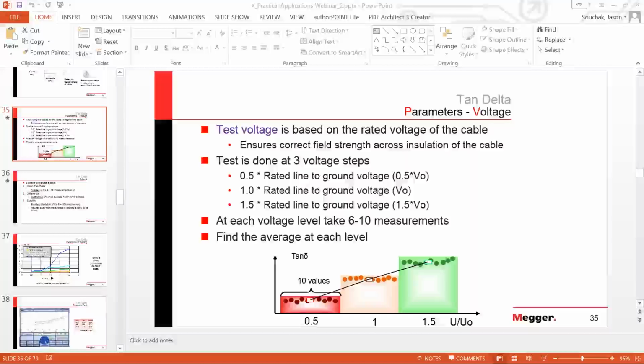So that's why temperature is certainly one of the fundamental aging parameters that affect the insulation, and you might also have a combination of temperature but also mechanical, because as you well aware of, if you have a lot of changing temperature from changes in loads, you also get, let's say, thermal expansion and contraction. So you now also have the mechanical aspect of aging.